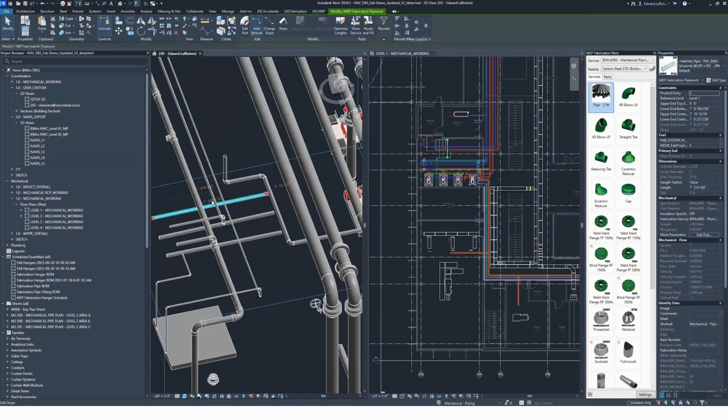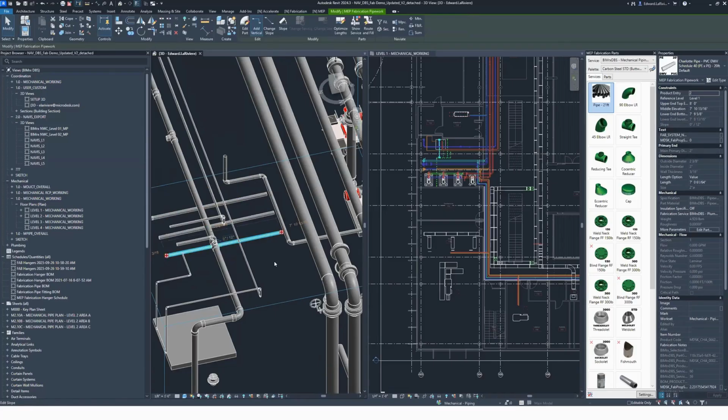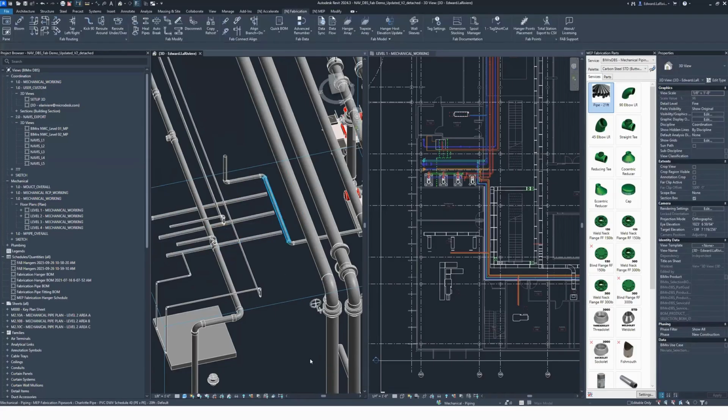If we take a look, I've got a 1/8 inch slope. I've got a 1/4 inch slope. And that third guy, no slope whatsoever. All lined up against a 1/8 inch main. Well, that aligned branch, couple clicks, lines both of those up. And we use that out of that box, trim, extend, and we're already done. No extra sections, no nothing. Just click, click, connect. Really, really smooth.